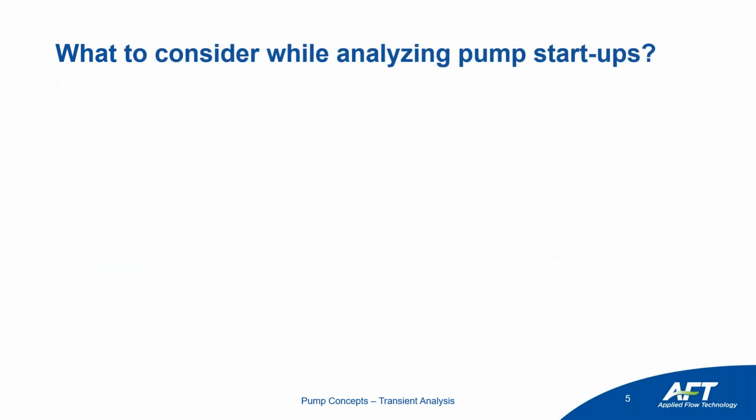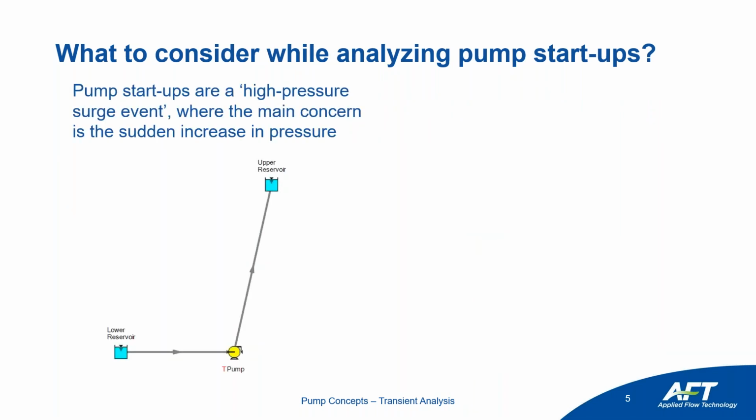So what do we want to consider when we're analyzing a pump startup, for example? We can think of pump startups as a high pressure surge event where the main concern is a sudden increase in pressure. Let's imagine that we have this system, again, a very simple conceptual example, where we're pumping from a lower reservoir, we have to overcome all of this static head, and we're using this pump to do it. So when this pump starts up, during normal operation, you have to see higher pressure at the pump to drive flow towards the upper reservoir, which means as it starts up, that positive pressure wave, that sudden increase in pressure, can travel through the system, can reflect similar to other high pressure phenomenon.